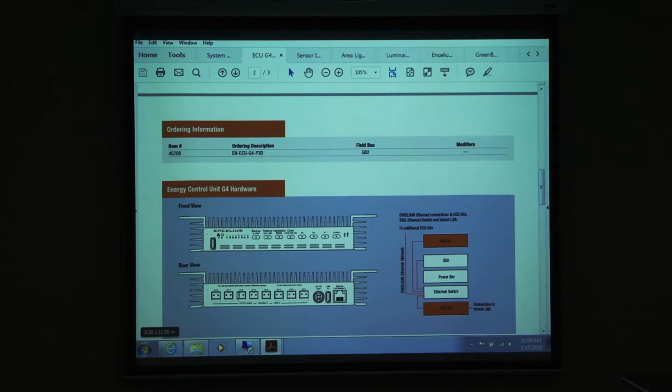So the more sensors you have on a channel, the lower that 100 number gets. That number is just a nameplate number for modules that turn lights off and on. People get confused: you say you can do 100 devices, so why am I seeing 50 devices on my channel? It's based on the current draw.